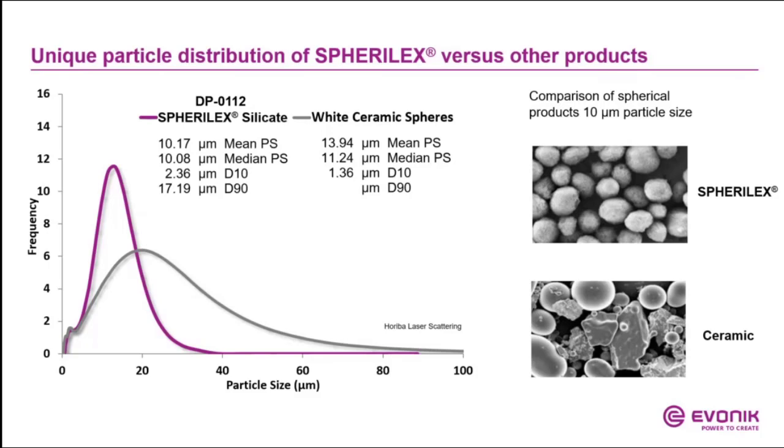In general, you can say the small particles cannot change your properties in the coating, or you cannot achieve the required properties. The big particles, on the other hand, can cause big trouble in your formulation. For example, when we look at the rheology, they can make trouble, or when we go in the direction of glossy coatings, they can influence the gloss in a negative way, or other properties can be influenced negatively by coarser particles.